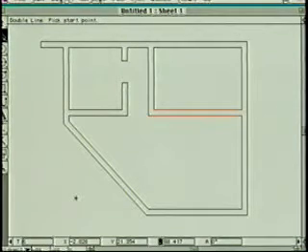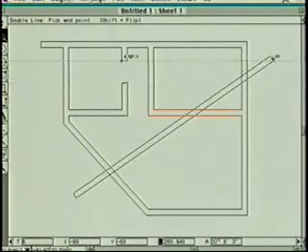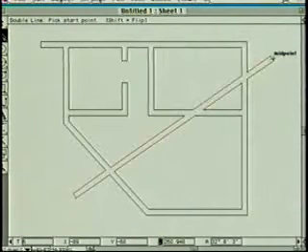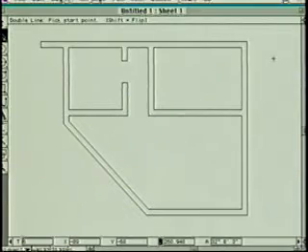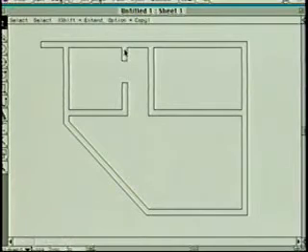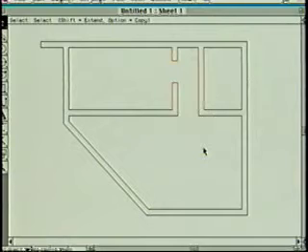It will even do such bizarre things that for some reason I put in some strange wall like this. It heals all of those. And then if I were to delete that wall, they heal as well. So this is why we call it a Smart Wall tool. It makes it really nice to just lay things out. And for changes, if I say, well, this hallway really ought to be over here, everything heals.